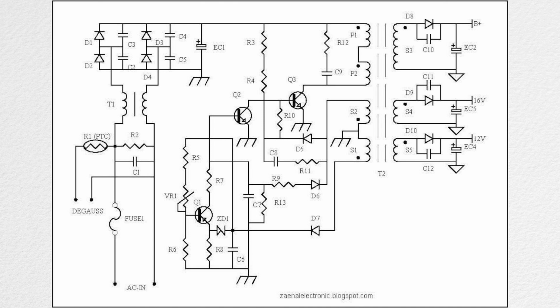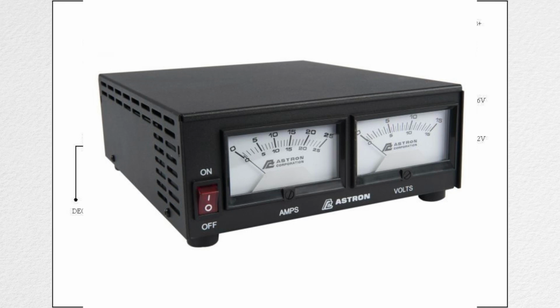When I say super fast, we're talking in the kilohertz range, not the hertz range like in a normal power supply, where the wall outlet is at 60 hertz. Inside of the switching power supply, we're talking about 40 kilohertz in switching speed. And again, the trade-off is size.